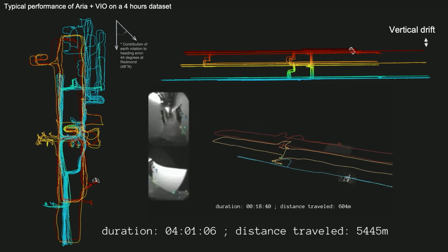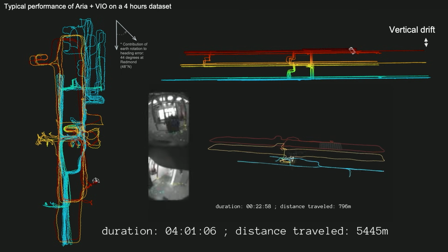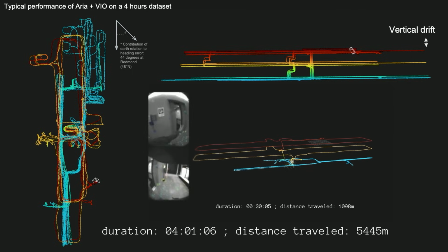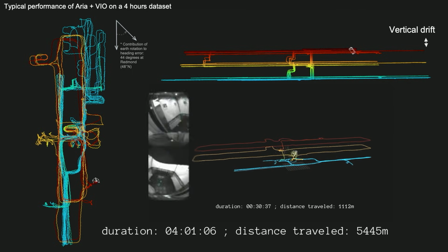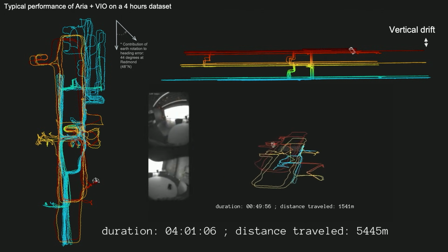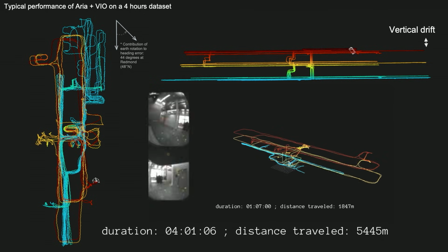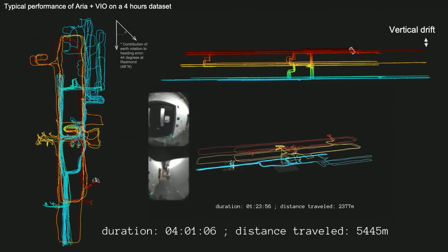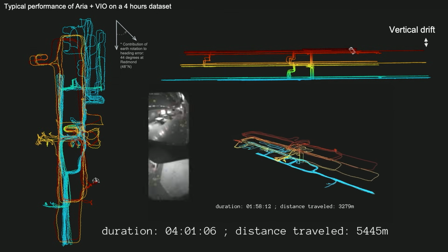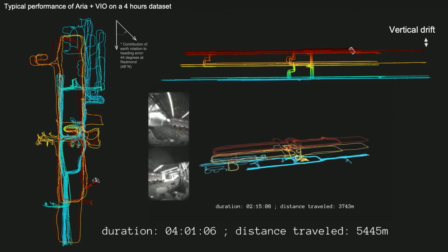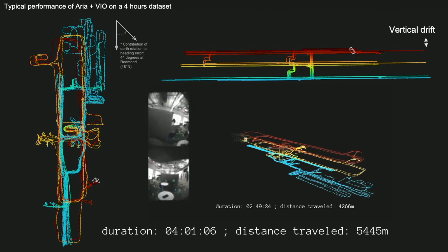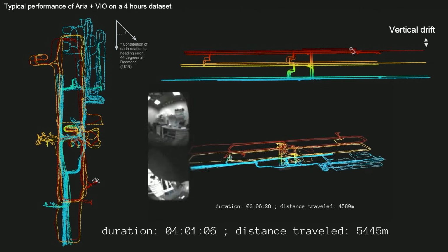What is interesting with that trajectory is it's over 4 hours, and over 4 hours, the Earth is going to be rotating. The rotation rate of the Earth is roughly 15 degrees an hour. So here, that means while you were recording this trajectory, the Earth rotated 60 degrees. That means if you have a perfect gyro and you integrate it without taking into account that the Earth is rotating, you will make an error of 48 degrees. You have to compensate for some latitude effect.